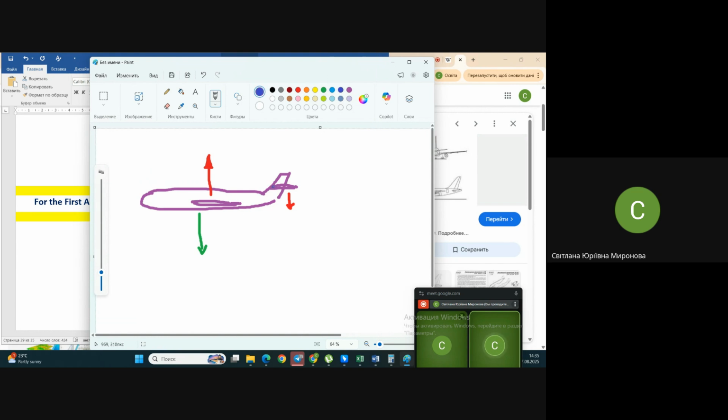It means that if you understand via the center of gravity, the moment of lift of the wing, with this so-called arm, let's call it L of wing, or better maybe to use a little literal. The moment that the wing creates should be equal to that of the stabilizer, because it's counterworking to the other side.